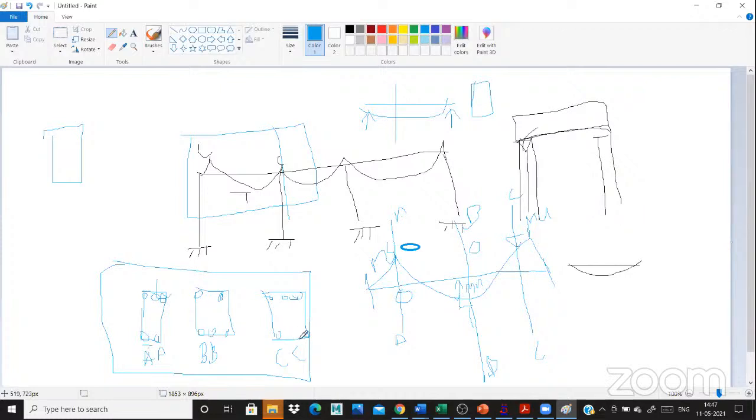It is low. And this is C. Then he provided the compression and tension. The tension is 0 and the compression is high, so I provided the top zone. This is our neutral axis. Now understand how to take the cross sections and how to provide reinforcement details. This is the same procedure that STAAD Pro will give as the result also. Okay, I will give some points.